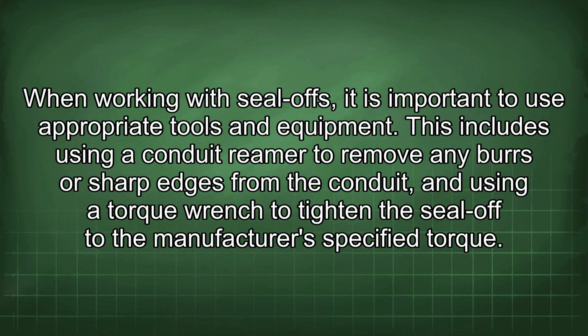When working with seal-offs, it is important to use appropriate tools and equipment. This includes using a conduit reamer to remove any burrs or sharp edges from the conduit, and using a torque wrench to tighten the seal-off to the manufacturer's specified torque.